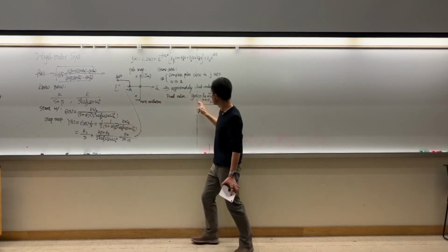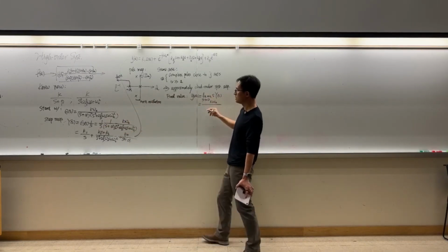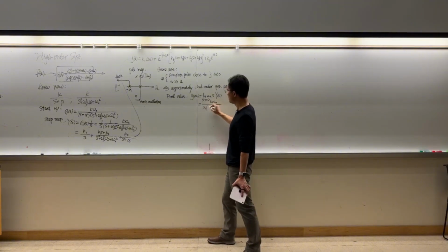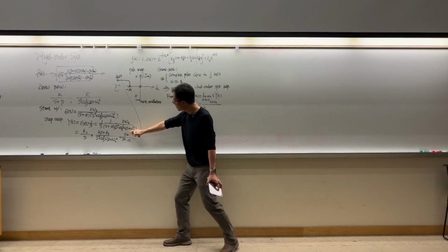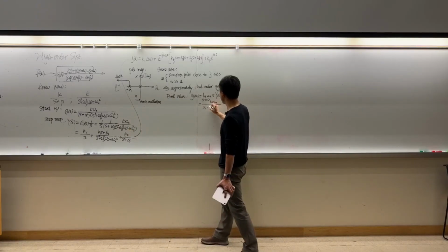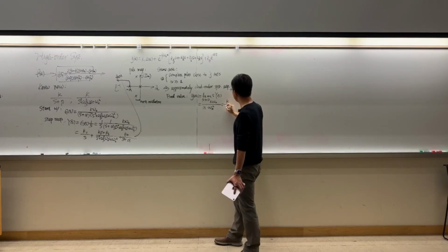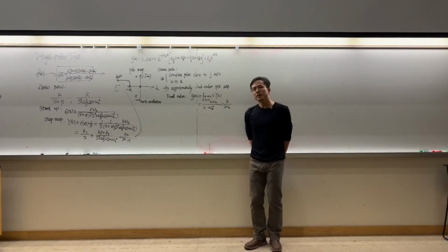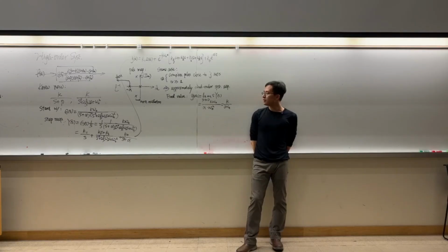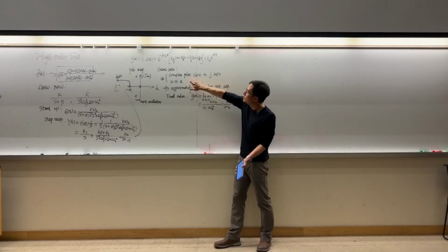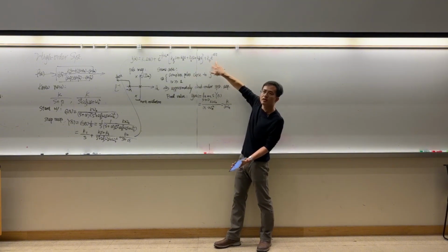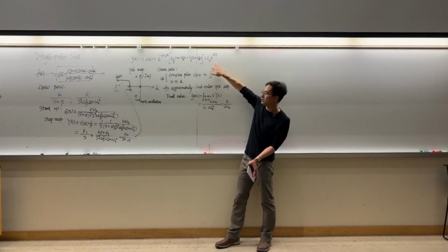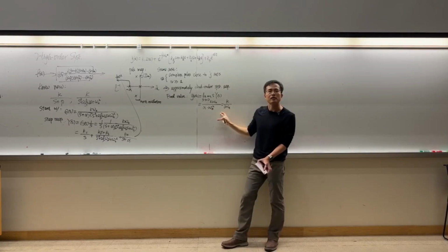This s cancels with this s, so it's alpha times 0 plus omega n squared, so alpha times omega n squared, which equals k over alpha omega n. That's the point you need to be careful about. Although the intuition applies and the transient response is very fast, alpha influences the final value.